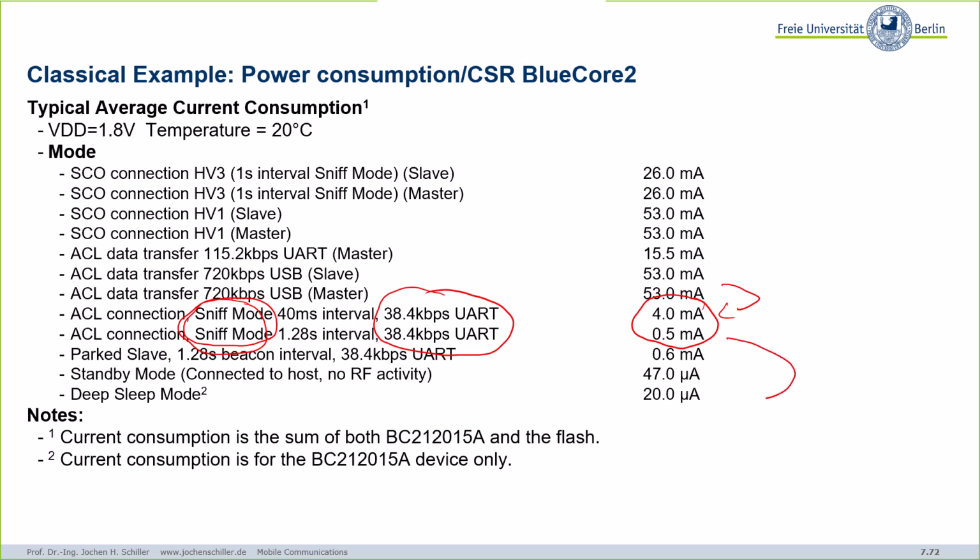And you see what happens if you're really in deep sleep. Then you go further down, to standby, etc. But you do not follow the hopping pattern. In sniff mode, you still follow. You hop through the channels, but you do not send anything, and you don't have to receive anything. It's just that you follow. Basically, you continue to count, or you calculate which is the next channel, without sending, receiving, or whatever. And this does not consume that much power.